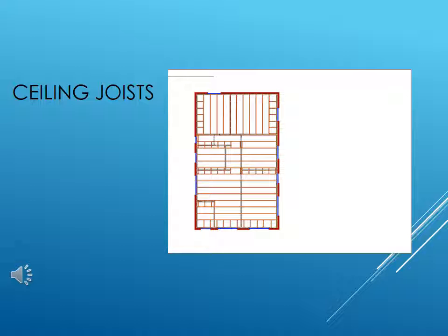As you can see, this breaks it down really clearly, but this is the first part that you would actually have to calculate, is the span of the ceiling joist, also the span of the ceiling joist running, in this case on the slide, vertically, what that distance is, or do we actually need to fit some other beams in here to enable us to use a reasonable size or a cost-effective size ceiling joist such as 90 by 35.